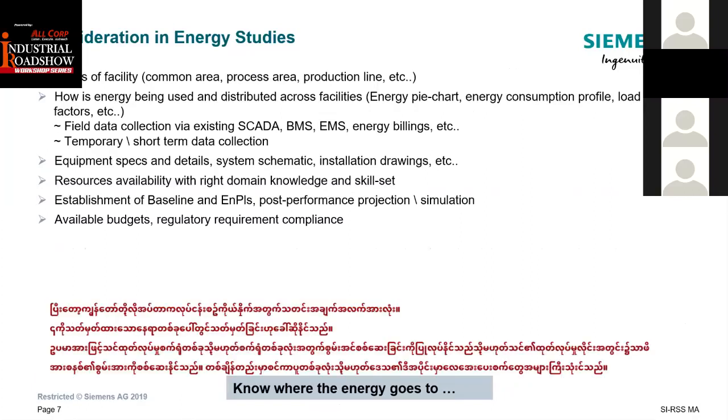And what is needed in all these audits? What we need is all the information for the process itself. By the way, an energy audit can be defined on a certain location basis. For example, you can carry out an energy audit for a whole production plant or full facility, or only within your production line, such as the compressor system.